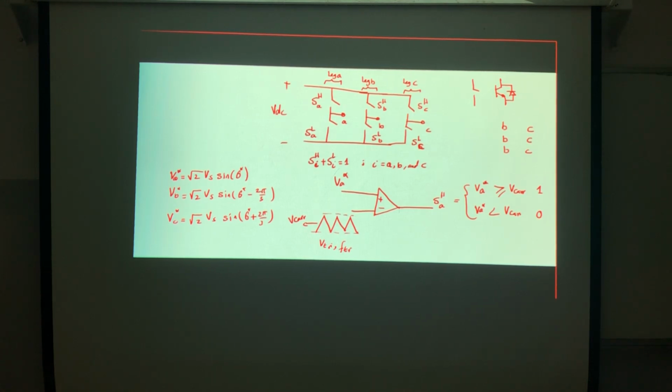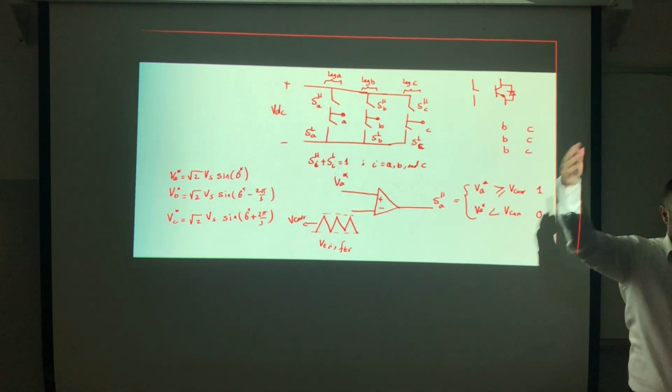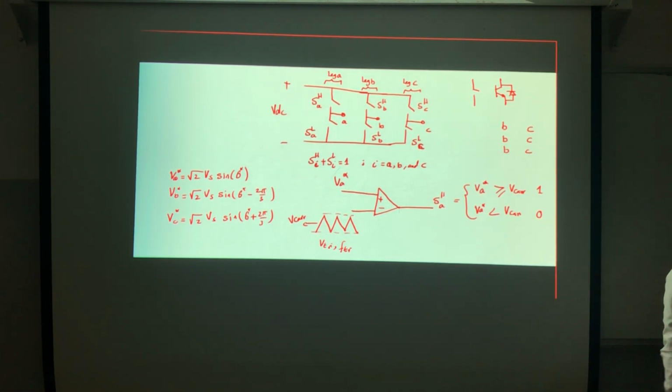If the upper switch is on, the lower switch should be off. Otherwise, I will do a short circuit, or what we call shoot through. So simply someone will say this means that I need to do an inverter here, and this would be the lower switch of leg A. This is how we can generate the gate pulses for leg A.